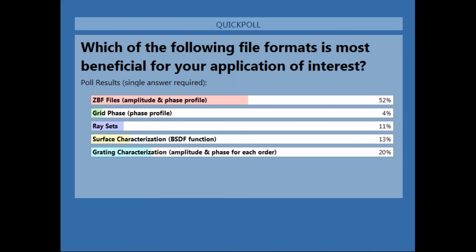And so I see another question. How to model off-axis imaging? There's a sampling problem with off-axis high-order polynomial phase profiles, and how do you solve that sampling problem? So in OpticStudio, when you're using the physical optics propagation tool, at each surface, inside of the surface properties, you can actually resample, and you can either choose to let it automatically resample, or you can choose which sampling you want.